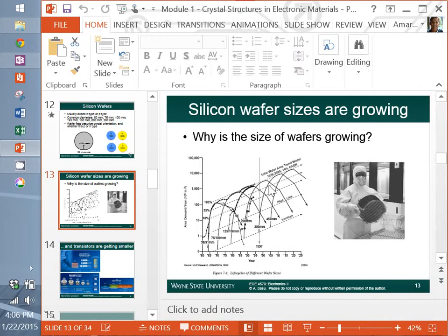When the transistors are 10 nanometers, a piece of dust might be 1,000 times larger than the transistor itself. So you can imagine that in the foundries where these things are made, you can't have any pieces of dust. And so they have these things called clean rooms. We have one here. Ours is probably a class 1,000 clean room. That means there's 1,000 particles per cubic meter or cubic feet, I can't remember which one it is. In these types of situations, they have class 10 clean rooms or better to prevent any type of dust particles, any type of contaminants from getting into the wafer.